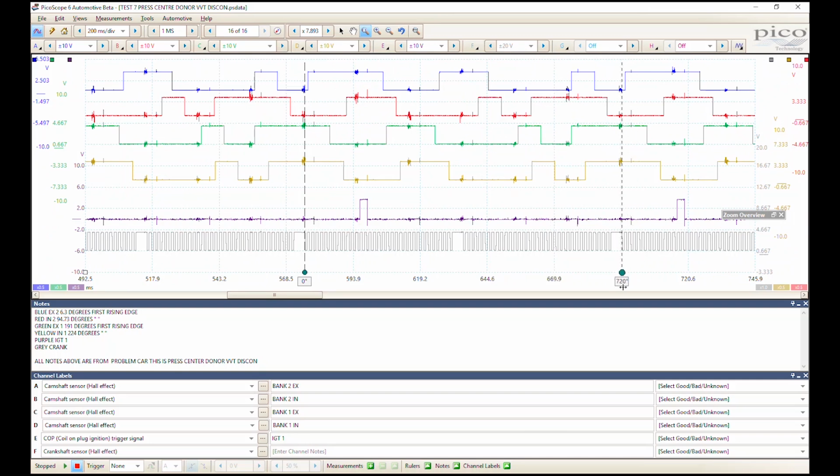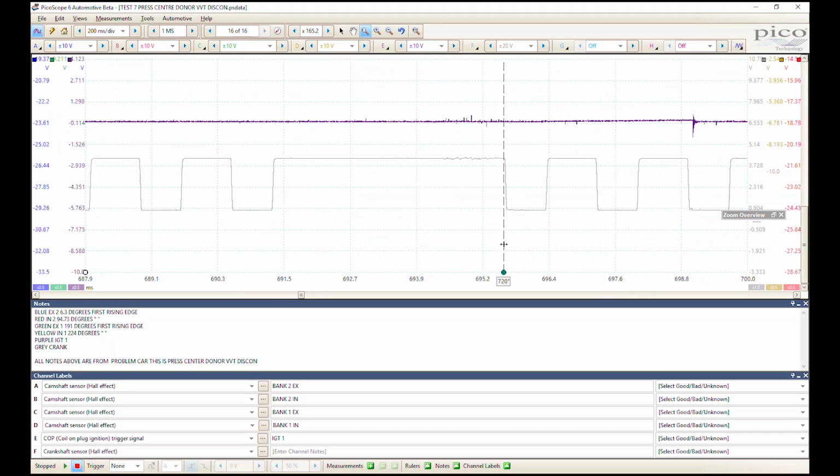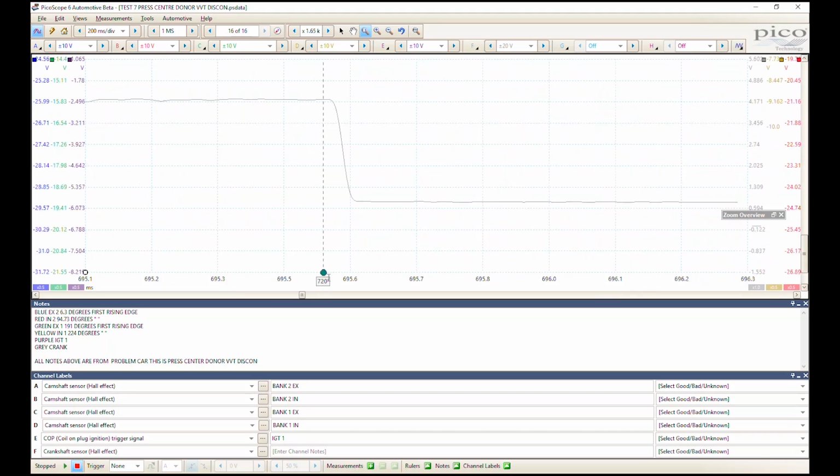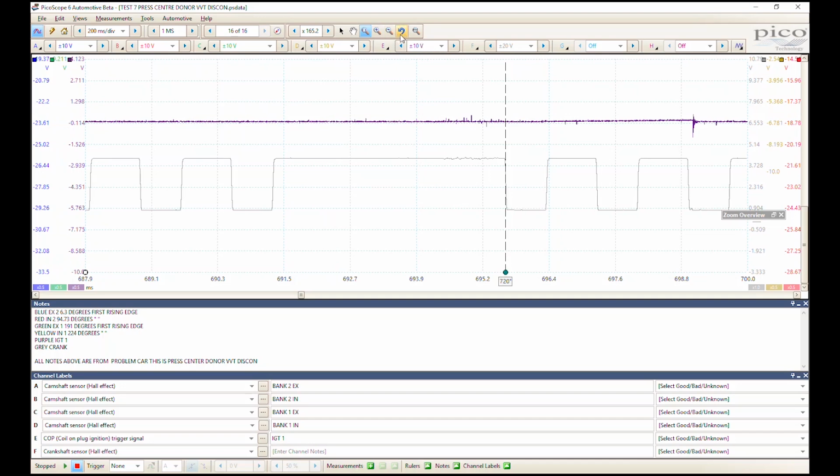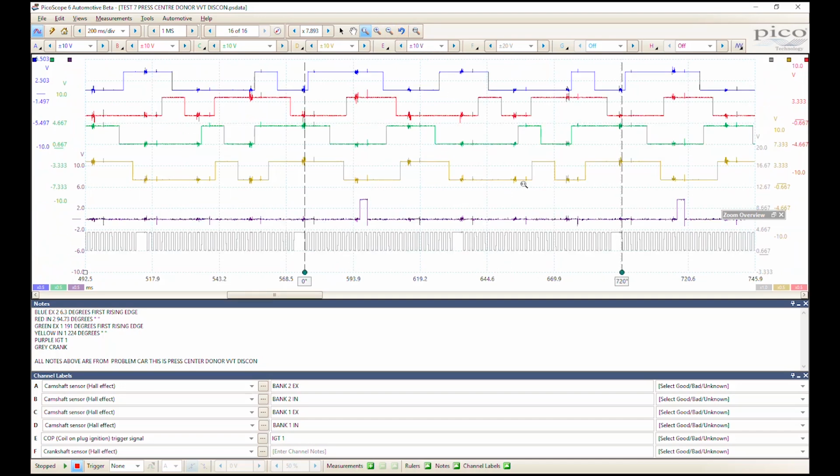It is our engine reference point, crankshaft reference point. That's not TDC. It might be all pistons in line, it might be pistons 10 degrees before top dead centre. You'll have to refer to the manufacturer's specifications for that. Okay, notice this additional noise on this waveform, and it looks as though the donor may have been on direct injection because the amount of noise increases when you go from port injection to direct injection, because if you remember the donor was an RX 350 hybrid, I think it was.